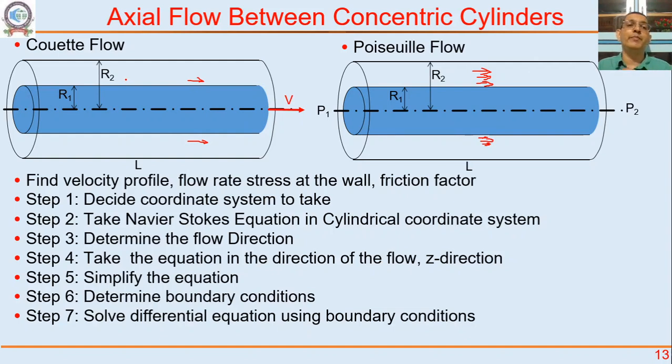Application. So imagine you are making a wire. Let's say this inner rod is like the wire and this liquid is like the molten polymer. So when you draw that wire out, the molten polymer flows along with this rod, along with this wire. Now once it is outside, we can quench and solidify the polymer. You will have a rod coated with a solid polymer. That's how insulated wires are made. Copper wire is there, plastic insulation is there, right?